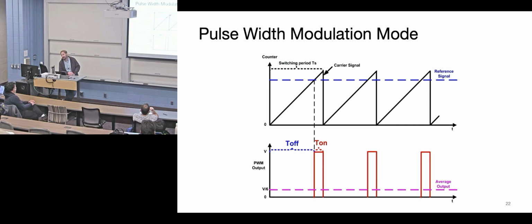Yeah. What percentage of the pulse is on versus off? Yeah. Ratio on off. Yep. So this would probably be a pretty small duty cycle compared to the off time. There's always this arbitrary factor of do you mean duty cycle high or duty cycle low? You could say, what's the duty cycle of this being low versus high? We'll just always assume we're talking about the duty cycle as the part of the time that's on. So for example, would you say maybe the duty cycle here is 10%? Yeah. Feels about right.